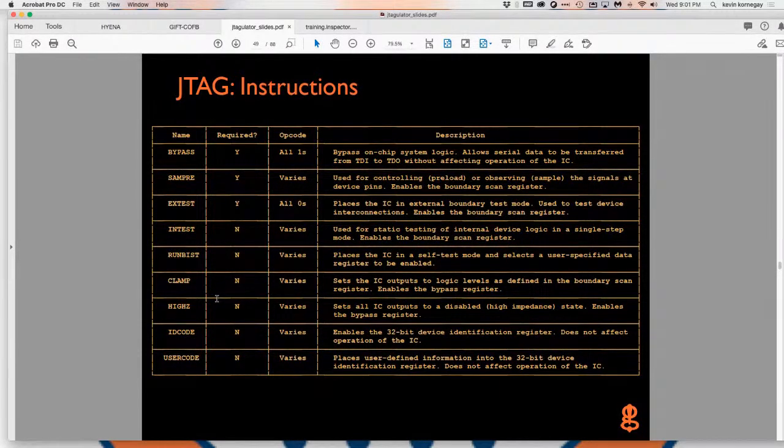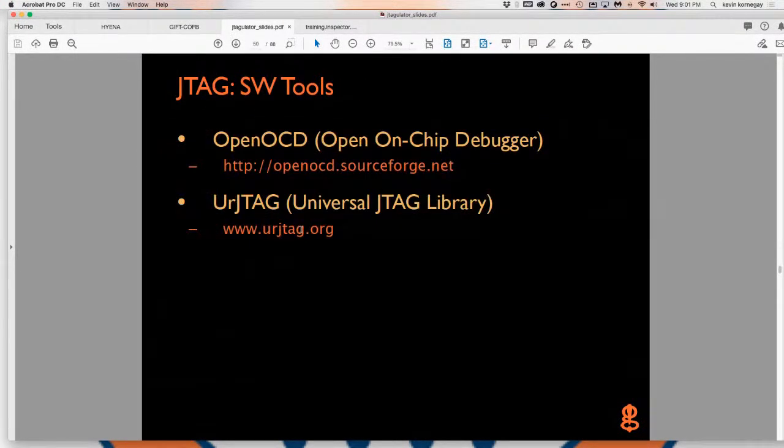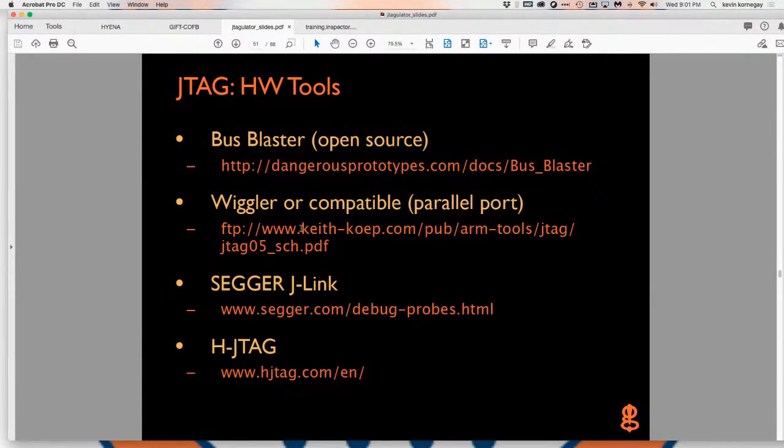So in other words, when it's in a high impedance state, the processor, which is the brains, is not going to respond to any input. The device appears like it's dead, but it's not. It's just in a sleep state, but the user doesn't know it. An adversary could do something like that very easily if they had control of the JTAG. But the JTAG attacks require that you have physical access to the device.